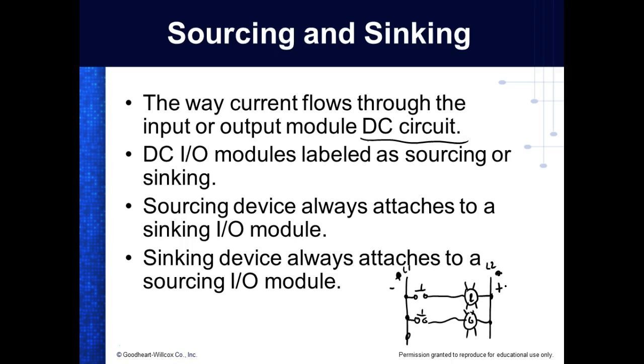You understand? So this came up through DC, through digital. And we really don't need to understand how digital circuits work. But if the minus is used as the common in PLCs, this is referred to as sinking. And if the plus is used as the common, this is referred to as sourcing. Sources like power and things like that? No, it's just the common. Current has to flow through the load to produce work.